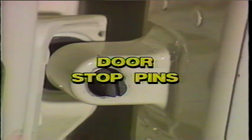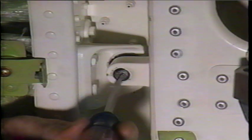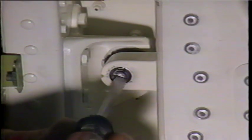The next adjustment is the door stop pins. The objective is to obtain the proper clearance between the door stop pins and the stop pads on the body. On stop pins that can be accessed with the door closed, close and latch the door. Extend each stop pin to just touch the stop pad. Back off the stop pin 1/2 turn.